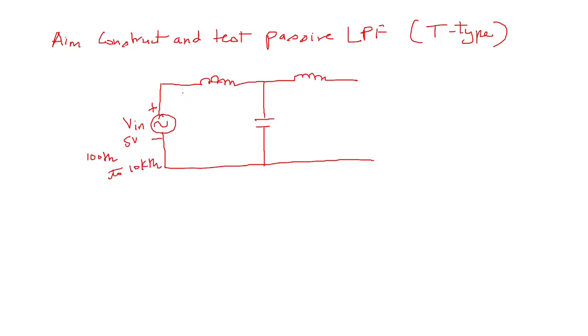Okay, so here this is L by 2, this is L by 2, this is C, and here we will have a resistance which will be your output resistance R0, which will be taken as 600 ohms, and here you are going to see the output on CRO.